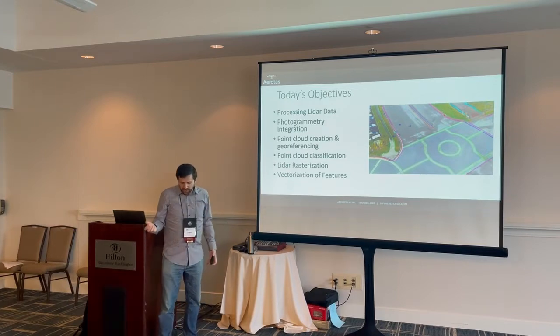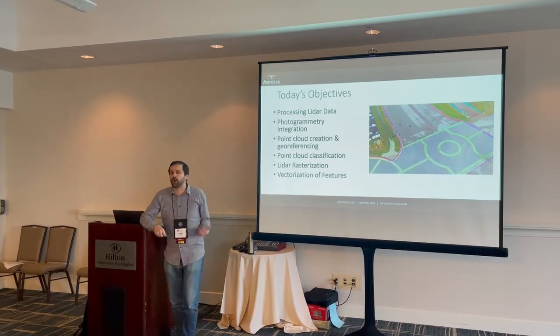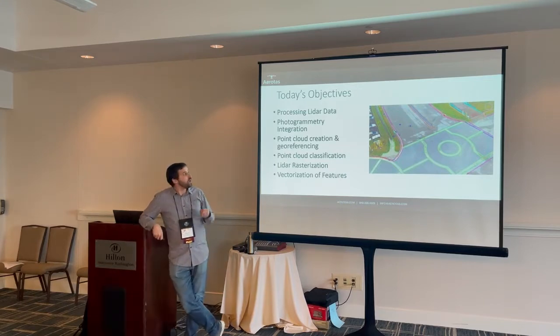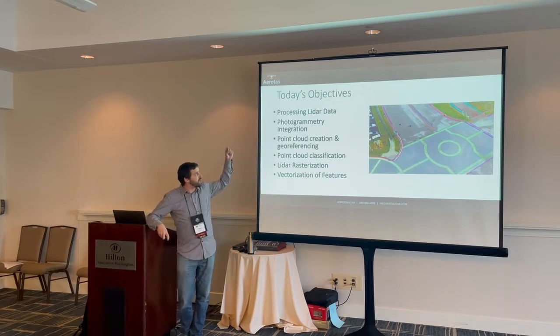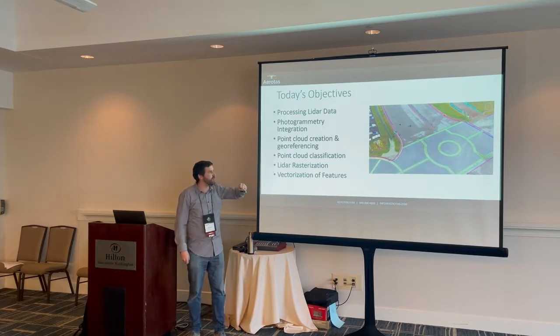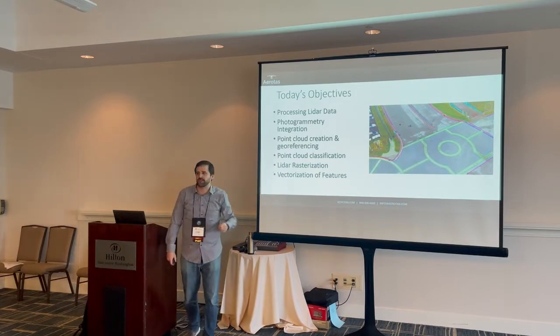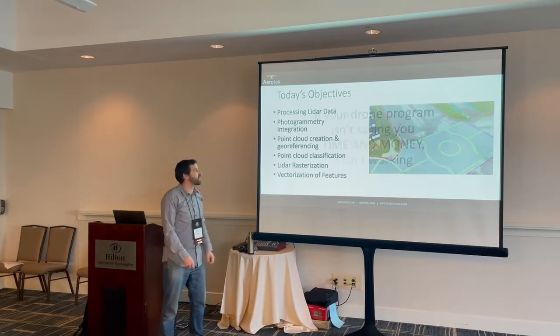Because as we've talked about, photogrammetry and LiDAR integration is what we think to be a very key part of being successful with LiDAR. We will be talking about photogrammetry a little bit as well. And then the actual LiDAR parts of the workflow, that's going to be creating and geo-referencing the point cloud, classifying the point cloud, rasterizing your LiDAR data into raster data, and then vectorization of the features. If you don't know exactly what all of that means, you will by the end of this talk.